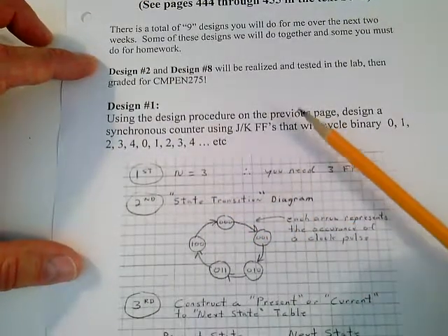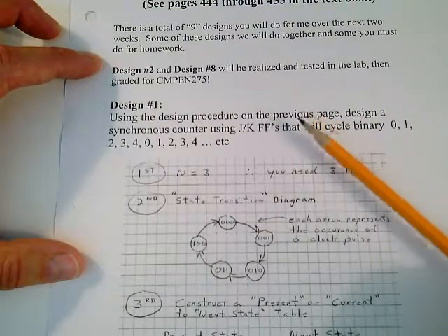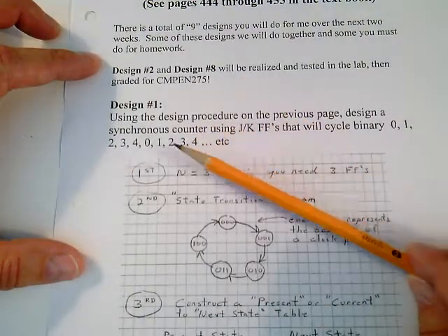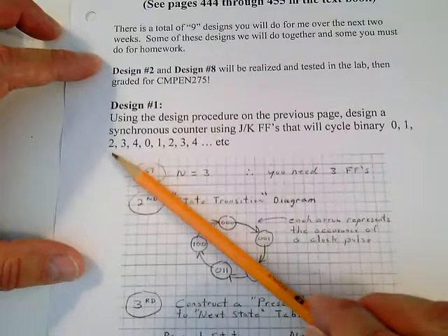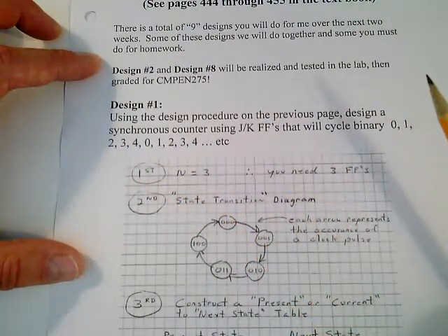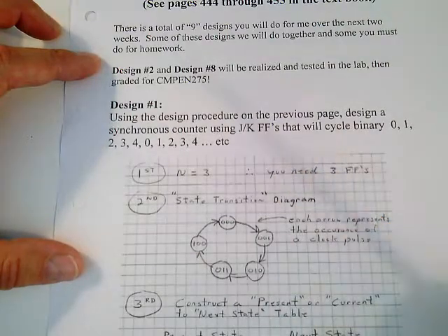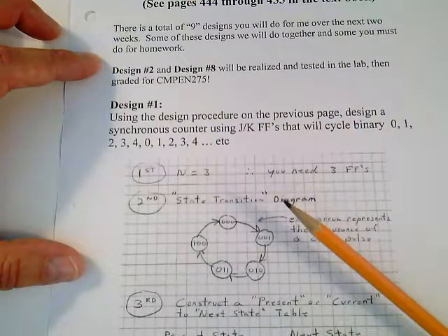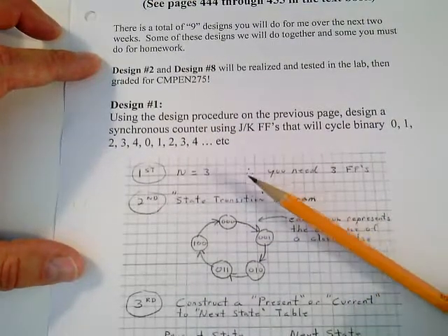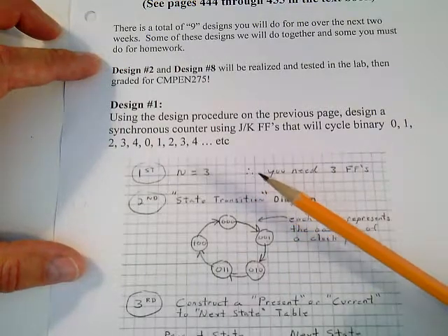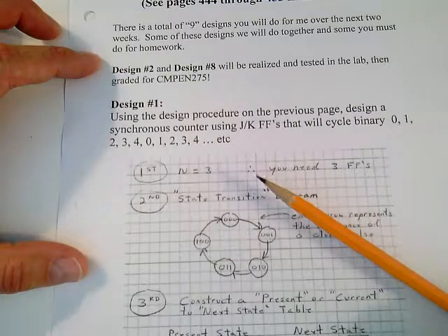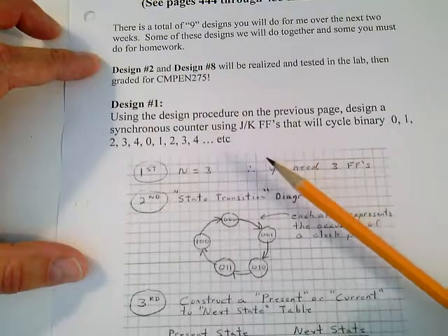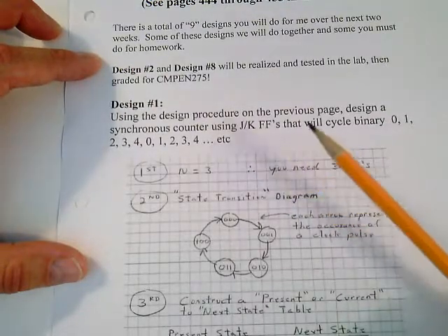Well, you could use the previous examples that I gave you, and you could decode the fifth state. Notice this is a 1, 2, 3, 4, 5. It's a mod 5 counter. So you decode the fifth state and you make it the 0 state. But we're going to show you another way of designing synchronous counters, and this way is more advantageous because it provides the same result, but you don't have to provide the decode. In a lot of cases, it's a simpler circuit from a standpoint of construction and cost.